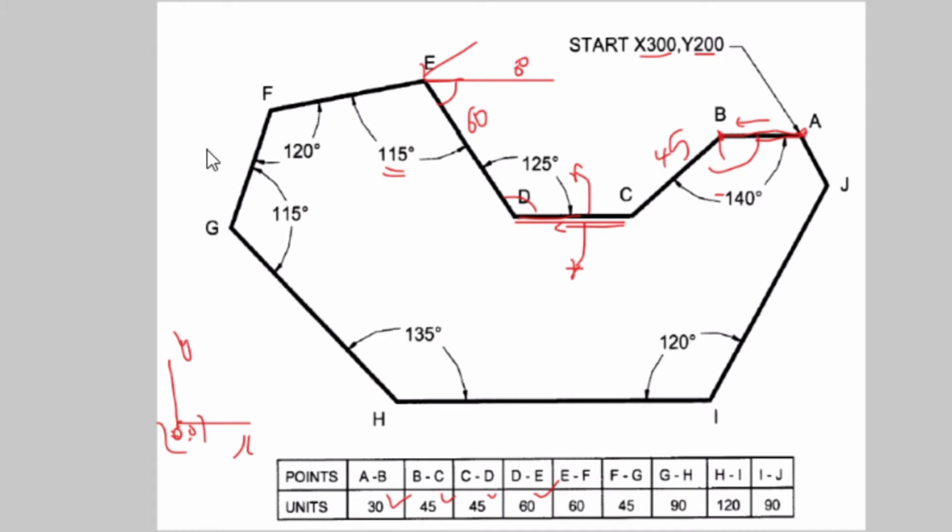So if you are using the global coordinate system, or the world coordinate system as per the AutoCAD terminology, that is the original coordinate system that you use, it is always counted from the X direction, the X axis. That means if you take this coordinate system and put it over here, let me show you how that looks like. This is the theory behind this idea.